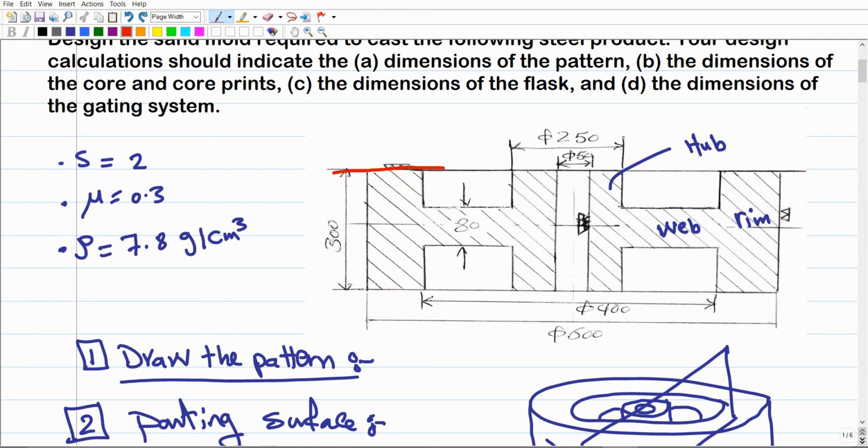One of them is a top surface and the other one is a bottom surface. We discussed in the previous videos that a top surface is the one that, if you look at the shape while it is oriented in the casting position, you're gonna see the surface. But if you cannot see the surface, it will be counted as a bottom surface.